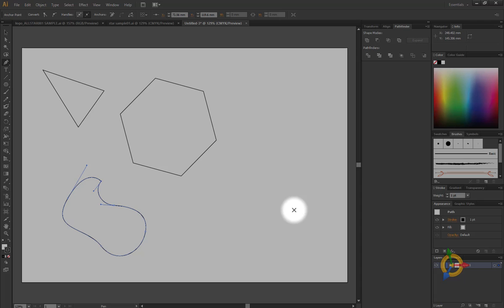Okay. Now, before I export this, what I'm going to do is make an adjustment to this file so that we can see if it makes any difference in Maya. So what I'm going to do is try and reset the center position, or this origin position, down here in the middle. And I'm going to see whether or not that impacts whether or not these shapes end up above the grid. If it does, it means that you can actually dictate where this is going to import into the scene a little bit in Maya, whether it's under the grid or over. So let's take a quick look and see if this setting will change.